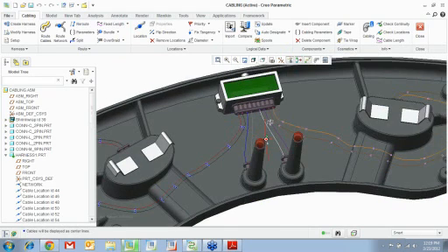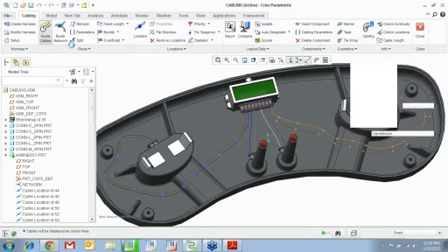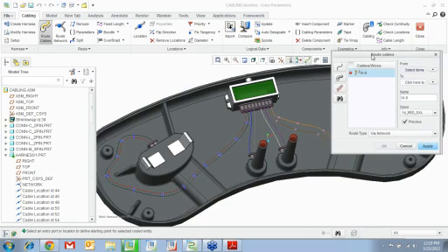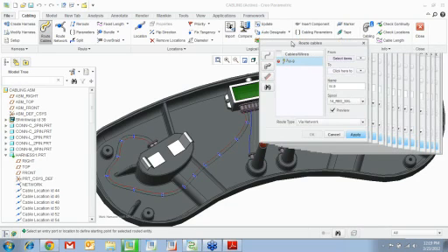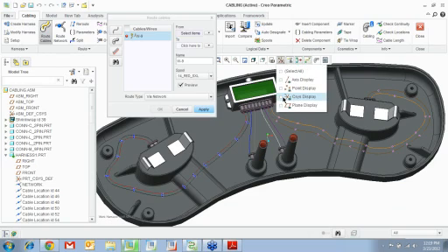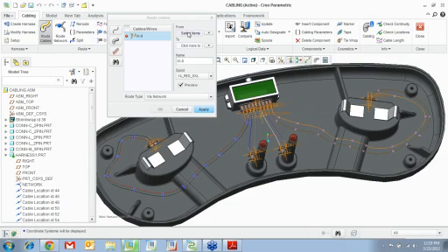So now before we get into that, I want to show you how to manually route the cable. Now I go route pipes, route cables. I'm going to go create a new wire. See that? Now I want to go from, you can add a location, or you can allow an undesignated coordinate system. So I'm going to just go ahead, turn on the coordinate system.